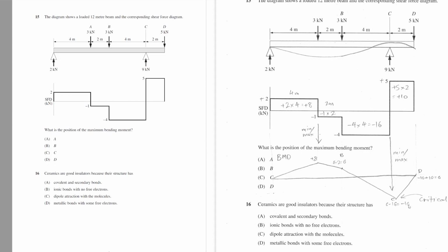It's worth also noting that in some circumstances, the plus 8 is very different to minus 10. So if we're talking about a concrete beam, the minus 10 represents the steel at the top, and the plus 8 represents the steel at the bottom, so it's relative to where this curve is. That's where we're putting steel in. The plus 8 means the steel that we need at the bottom is going to be based on 8 megapascals. And here we're going to need more steel at the top of this beam.